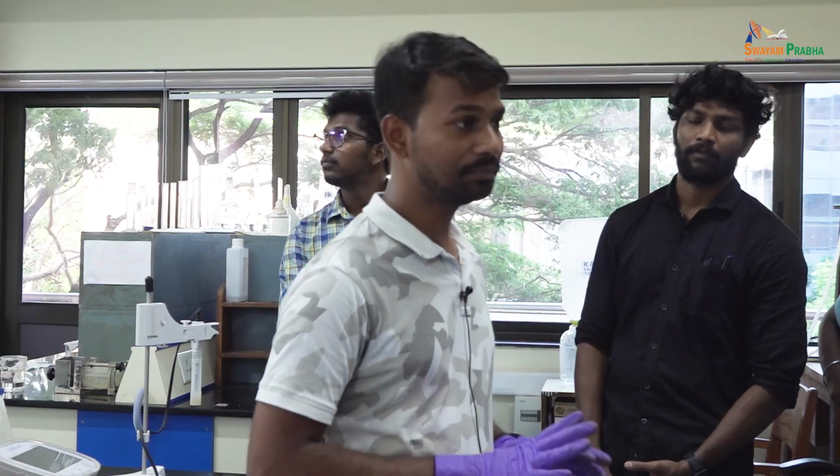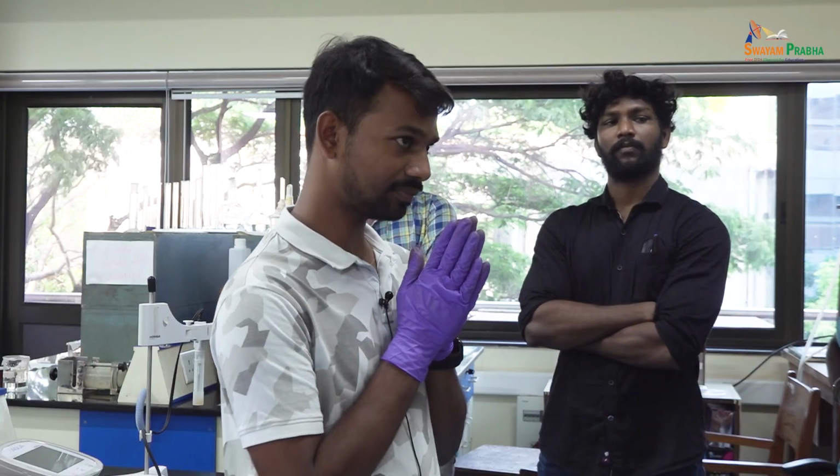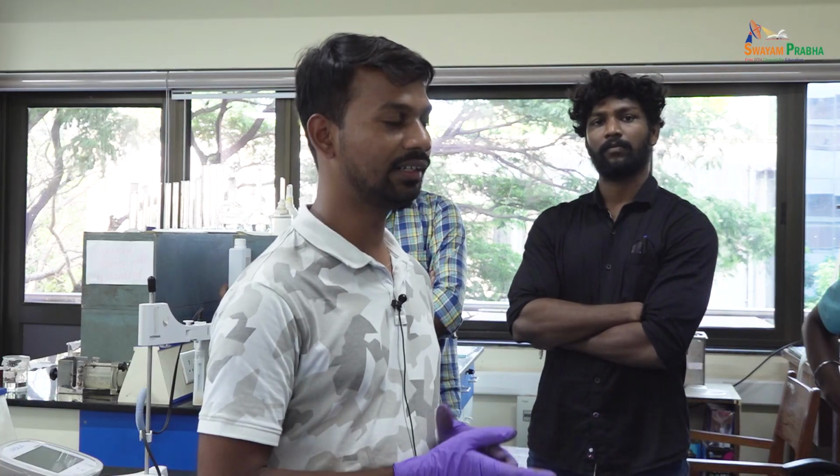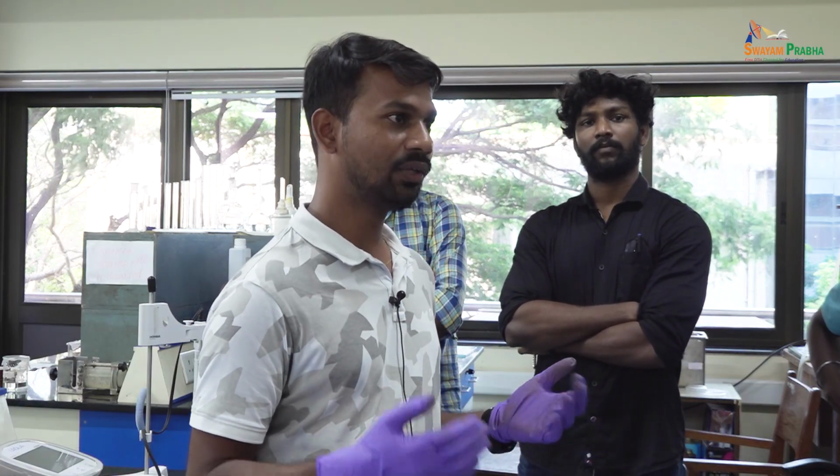I will do it for metallic bipolar plates and I will test it in fuel cell conditions. Usually what do you use in a fuel cell? Generally people are now using graphite only. It is very brittle and very heavy. High temperature it can withstand, but PEM fuel cells won't go beyond 90 degrees centigrade, so temperature is not an issue. It is very brittle and because of that it will be very bulky. We can't use it for automobile applications.